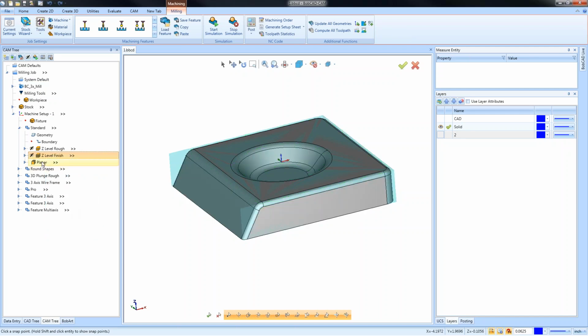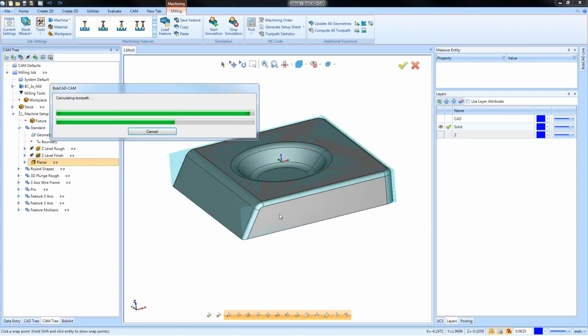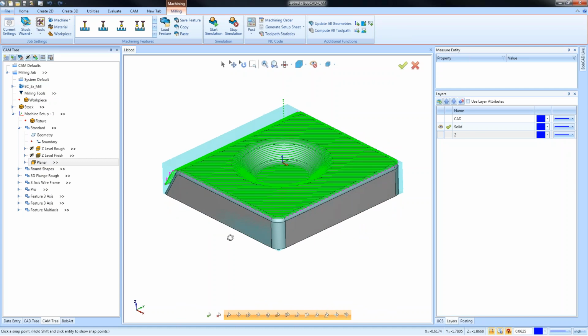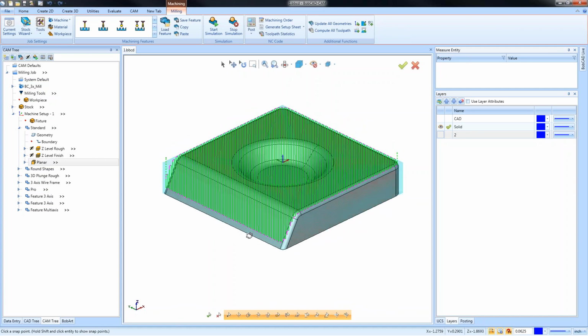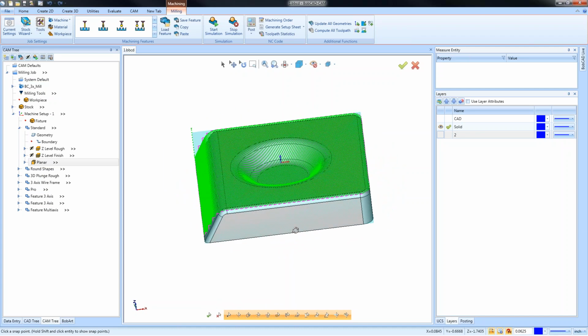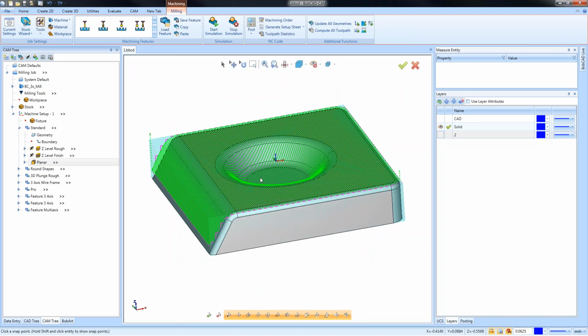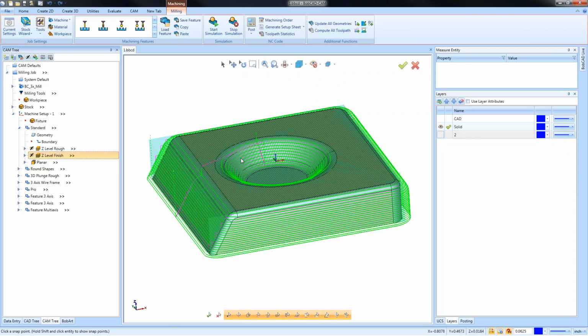Okay, so planer, this is like mowing your lawn. It's going to go back and forth at an angle. You know, this is a great toolpath to use for coverage. This is like a catch-all here. Okay, again, kind of the scenario that you'll look at here is where the surfaces are more steep, we're going to see that there's going to be greater scallops in this area. Okay, so where the planer does a good job on the shallow areas, the Z-level finish is going to do a better job on the steep areas.